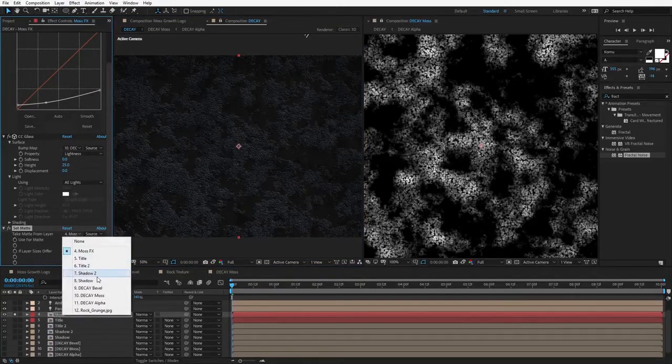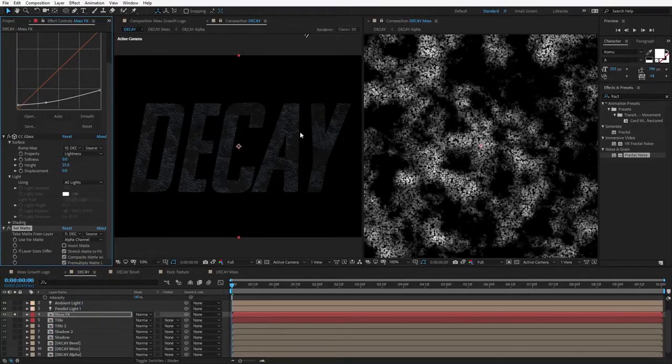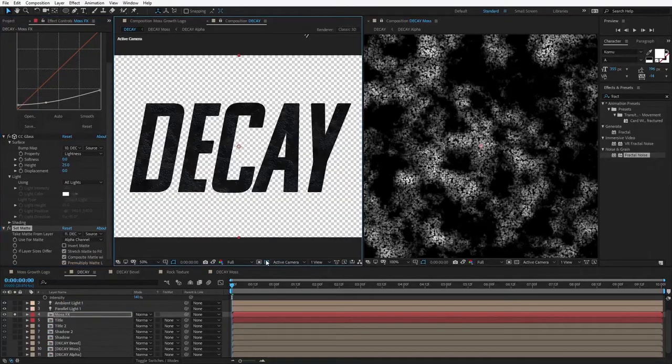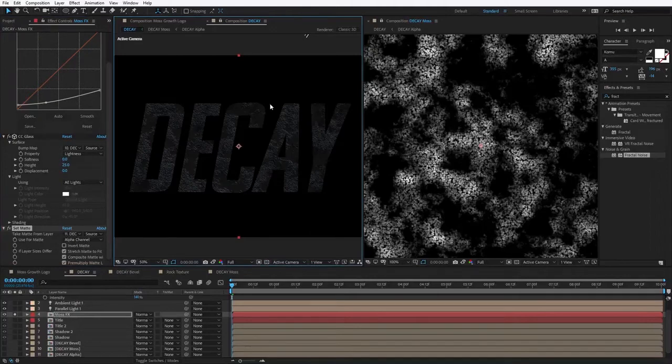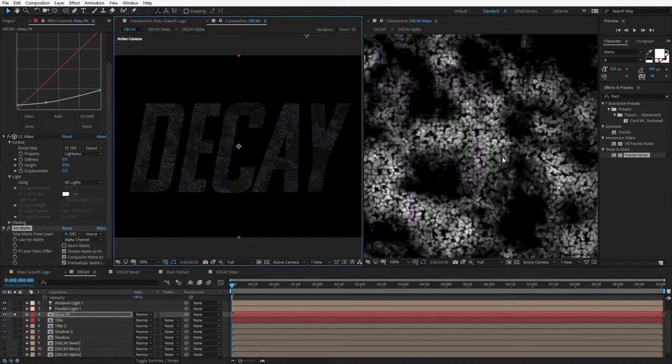Then we'll choose the original title alpha channel, the Decay Alpha Comp. And now we've created an alpha channel. But we actually want to do something even more specific. We want to create an alpha channel from this luminance.